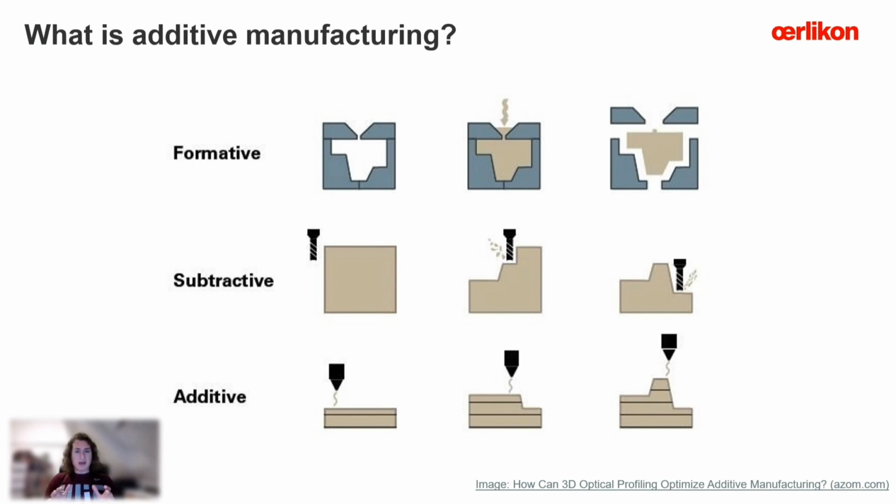In opposite to that, if we talk about additive manufacturing, what is a fancy thing about the technology is that we build a component during the process, doing this layer by layer deposition of a material. So in opposite to standard technologies, you do not remove a material, you add a material to build a component. And directed energy deposition is an additive manufacturing method which enables you to build a component layer by layer by adding an extra filler material.